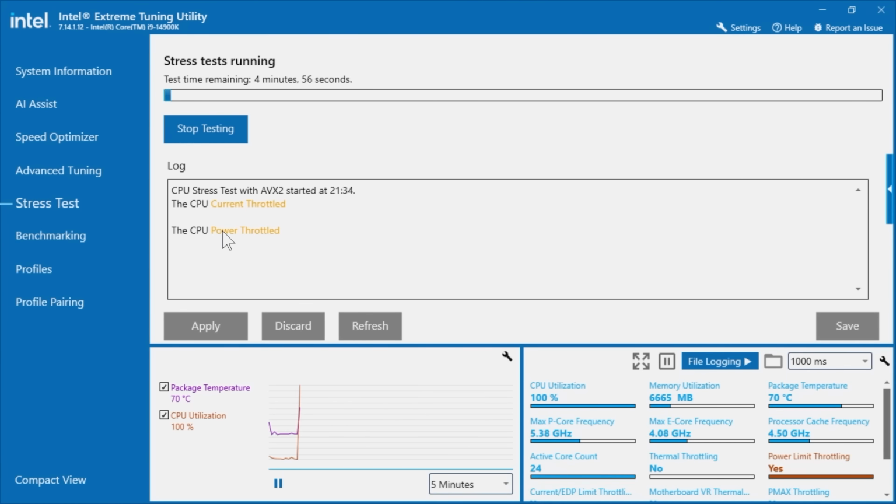So over the course of this video we're going to apply different undervolts just to show you exactly how it works and the process of actual stress testing, and just to ensure that our system is happy. Now remember, the package temperatures, even though still relatively low, actually will be much lower in gaming. So remember, the CPU is being stressed at a maximum level throughout the course of this test, and you also see the P-core frequency fluctuate as well. So remember, we synchronized all cores at 5.5. It doesn't mean to say that during the course of a stress test they're going to sit at 5.5.